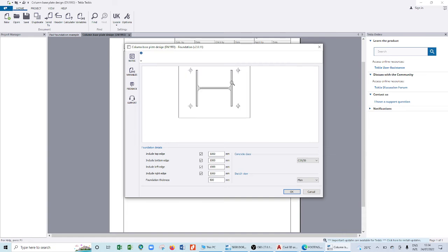Now remember we had selected the size of our base plate. We had 300 by 250. So meaning here, our column we had designed was 300 by 300. So on the width of that edge, if you are having 250, you deduct 300 minus 250, what do you get? You get 50. So meaning here the edge is 50.